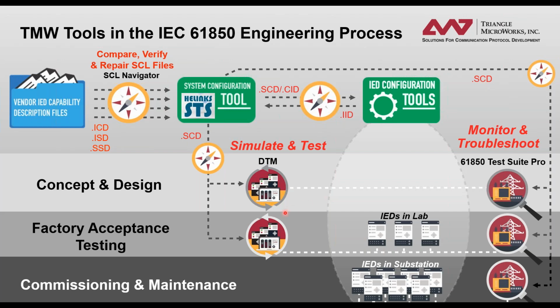And this is an overview of the whole process and how Triangle tools can help you be successful in these implementations. On the top line here is generally what we're going to cover in today's webinar. We start with the devices. Every device manufacturer selling a 61850 server needs to provide a file called an IED capabilities description file, which describes the data model and the services that that device provides. We'll see in a few minutes how our SCL Navigator helps those vendors produce that file.